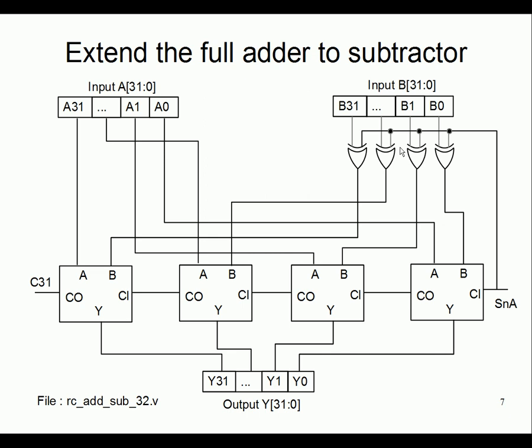If you understand this schematic connection, you should understand that these are pretty much uniform, replicable patterns. Bit 0 always goes to the first instance, the second bit goes to the second instance, the third connects to the third instance, and so on. So you can write a quick script which dumps all 32 full adder instantiations with the correct connections. The other way is to just hand type, cut and paste, and carefully change the indices.